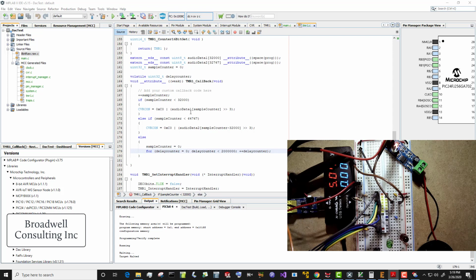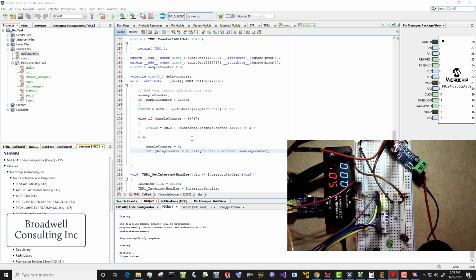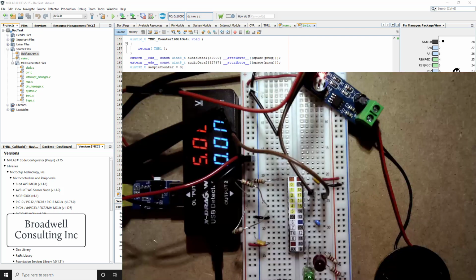16,000 interrupts is a lot, but not a horrible amount, especially when you've got such a little amount of code in it. And this microcontroller basically is going to be doing nothing else, but also driving some SPI traffic to drive our LEDs at the same time. That SPI traffic, I do anticipate that we'll use the DMA to feed the SPI with. So I'm going to go with this for right now. If it turns out we need to go a more complex route, map the flash into the shared data space and then point the DMA at that, we can set that up later, but I don't think we're going to need that. I'll hold my mic over it and you can determine for yourself what it sounds like.